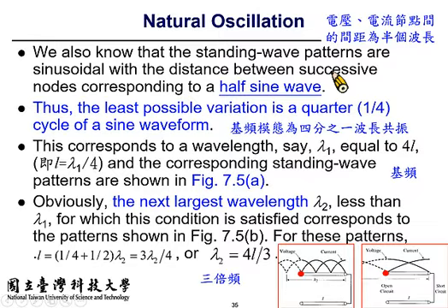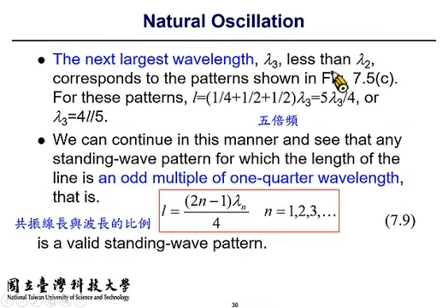For this frequency, the line length happens to be 3/4 wavelengths. And as you can imagine, the next one will be 5 times the frequency of the fundamental mode.